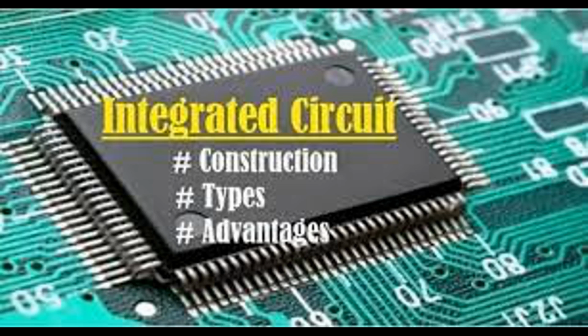Sequential logic elements. Some key sequential logic elements and concepts include flip-flops. These are bistable devices that can store one bit of information. Different types of flip-flops include D flip-flops, JK flip-flops, and T flip-flops. Latches. Latches are similar to flip-flops but can change their state based on the inputs at any time, whereas flip-flops change state based on the clock signal.